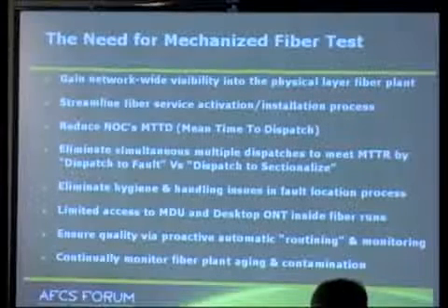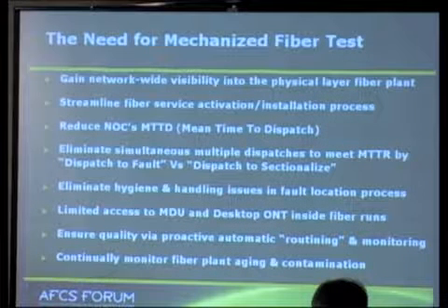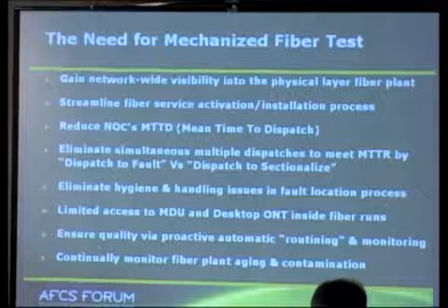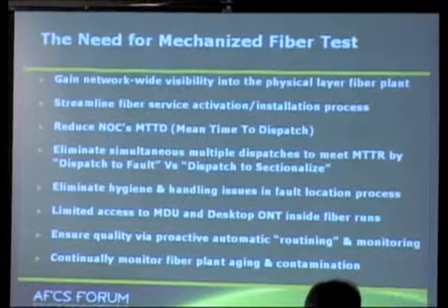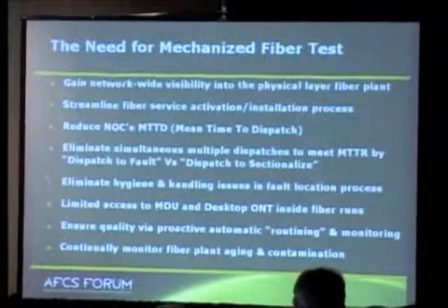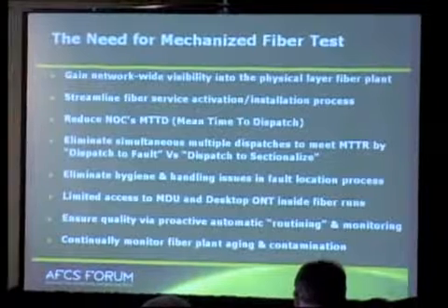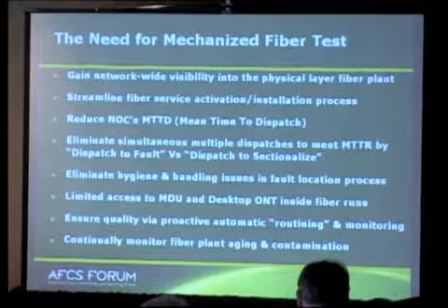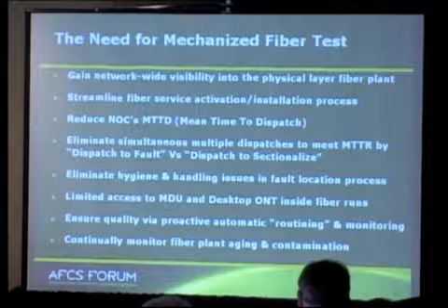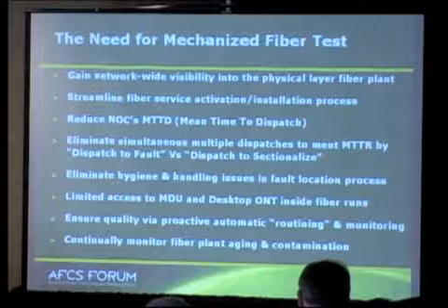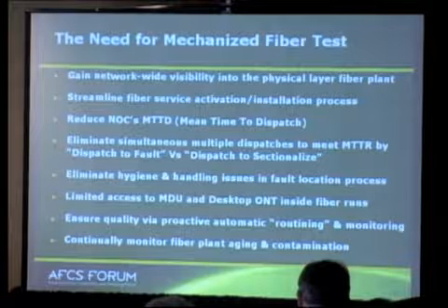But today, the outside plant technician is basically on his own to do that installation, and there are some challenges that they have in that process, and we'll get into that in more detail. Mean time to dispatch, especially on the larger carrier base, is a big problem because it's very hard, with the tools that they have, for fiber breaks and fiber problems such as connectors that get contaminated and microbends, to minimize dispatching the wrong work group.